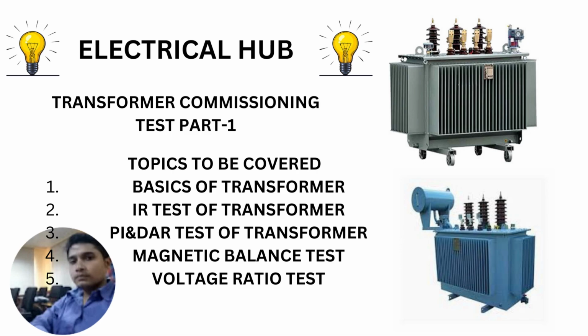Here we are going to discuss the basics of the transformer, the insulation resistance test of the transformer, how to do that and with what meter, we will discuss. Then the PI and DAR test of the transformer, polarization index and dielectric absorption ratio. Then the magnetic balance test and voltage ratio test.